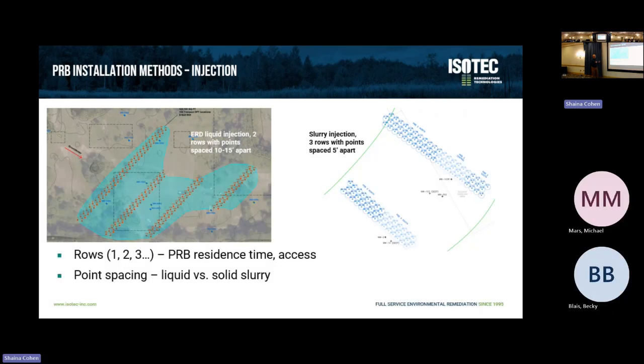Another key factor is, what is the desired residence time for the treatment that we need? It's not exactly comparable, and a lot of us talk about some of the benefit of contact time and the like, but column tests can also give us some of that information. Sometimes even just batch scale bench reactors of just what is the kinetics and how many hours or how many days might we need for the reaction to happen to have our desired contaminant reduction.